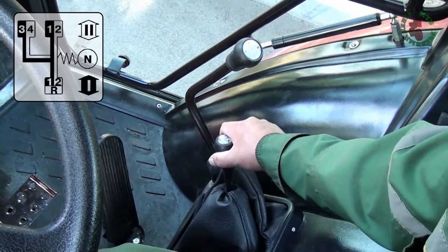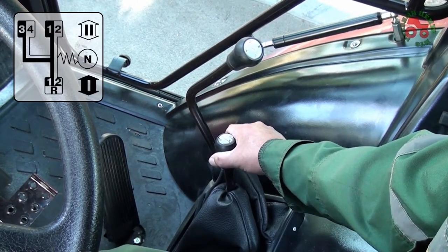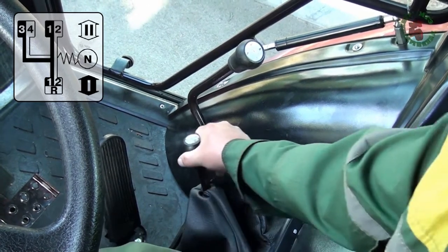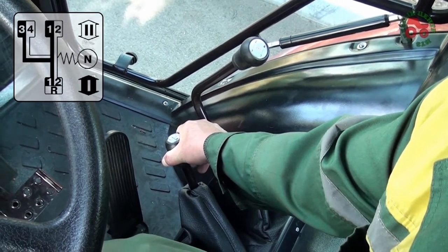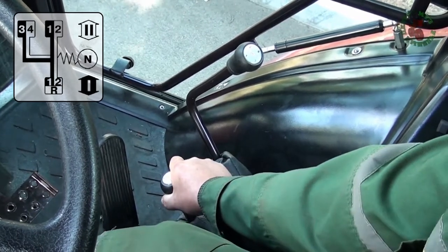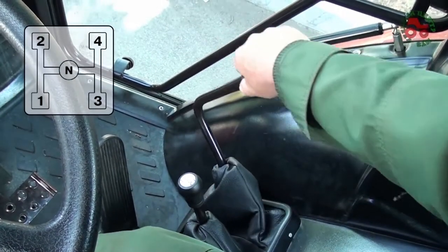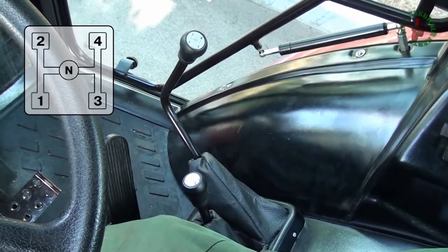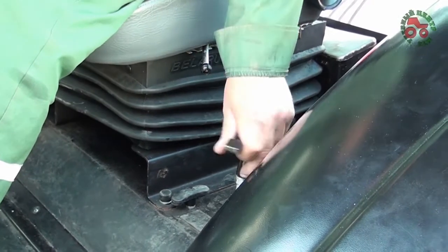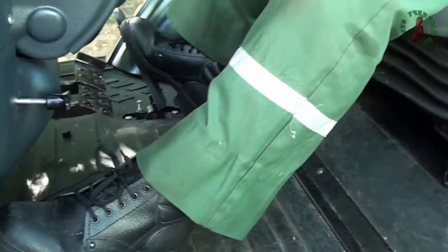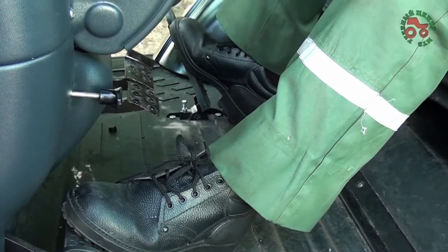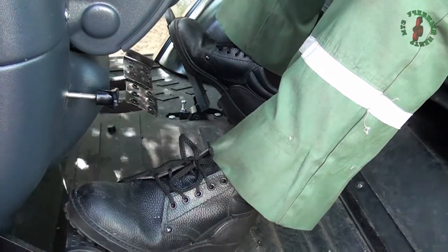Move the gearbox range lever into the extreme right spring-loaded position and pull the lever towards yourself or push the lever away from yourself for the lowest or highest gear stage. Return the lever into neutral position and then to the left to select the desired range. Select the desired speed with the gear shift lever. Disengage the parking brake. Release the clutch pedal slowly, increasing at the same time fuel delivery. The tractor starts to move.